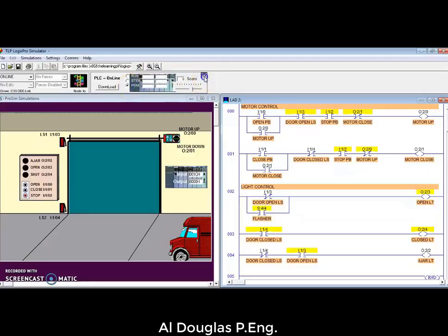There's a bunch of bits that are defined in the PLC that are going to flash at a bunch of set rates. I can show you a couple of them here. So just a couple of different addresses, and these are all going to flash at different speeds. If we look at all these going here, see those are all flashing separately. I'm going to do another one here with a 6 on the end. I think this one flashes at a pretty nice speed here. It's a nice slow flashing. This is the one I like to use. It's a pretty decent flashing rate. So we're actually going to call this one our flasher bit and use it in our program.